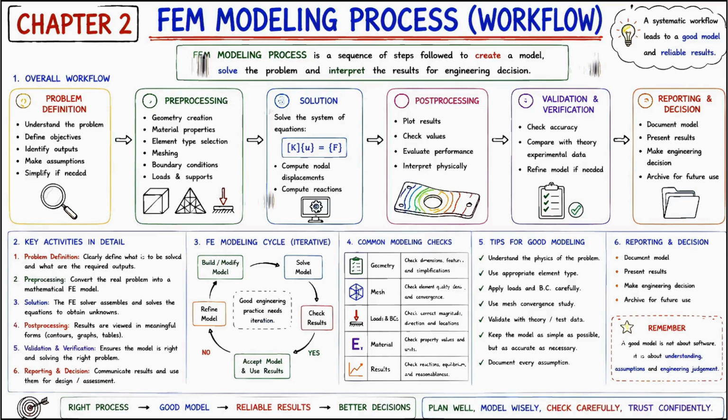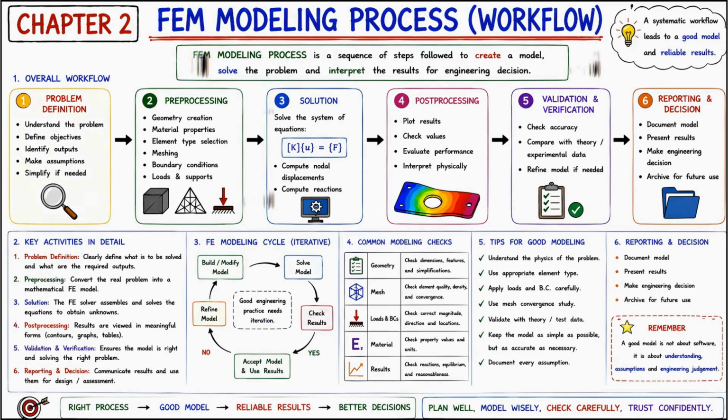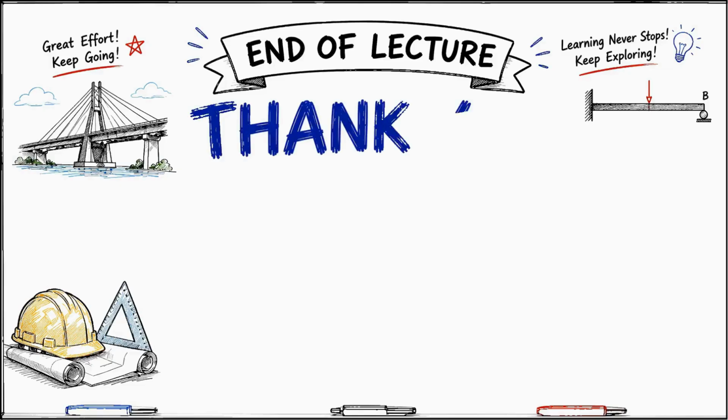The poster also highlights several important modeling checks. Always verify the geometry. Check mesh quality. Ensure that loads and boundary conditions are correctly applied. Verify material properties. Finally, examine whether the results are physically reasonable. Remember, a good finite element model is not just about using powerful software. It is about understanding engineering principles, making correct assumptions, and carefully verifying the results.